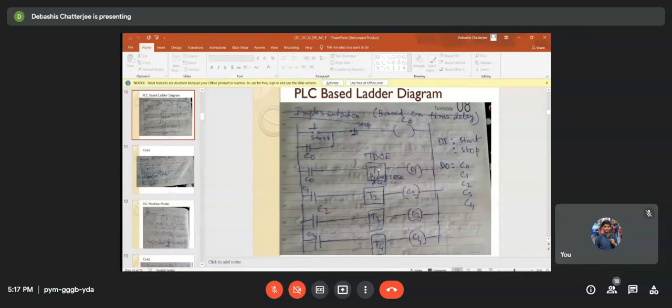As it equals the preset value, here it is 10 seconds, naturally the power will go through to C1. Now the C1 contactor will be on. So C1 is on now. When C1 is on, the contactor below is again on, again T2, TDOE, with a different time that you can also set. C2 will be on. So as a sequence, you can turn on up to C4. So C0, C1, C2, C4, all are on after some time, and the machine is running without any external resistance in the circuit. So this is the starting.